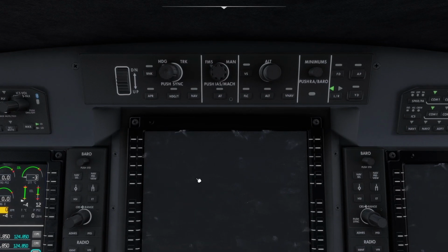If you press Shift 6, you will end up at the autopilot functionality. The autopilot functionality will be covered in a future episode, where you can, for example, change the active mode, like the approach mode, the auto throttle mode, because the aircraft has it, the flight level change option, and of course you can switch on the autopilot or only the flight director if you want it.